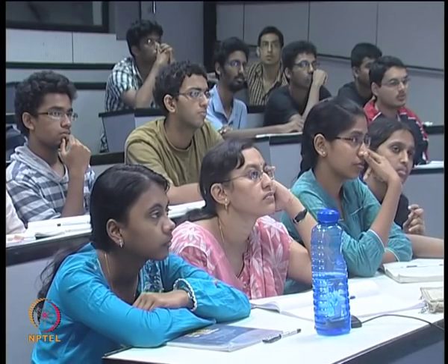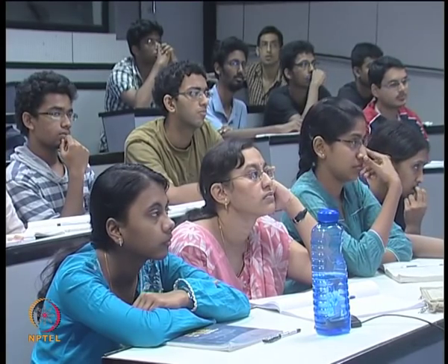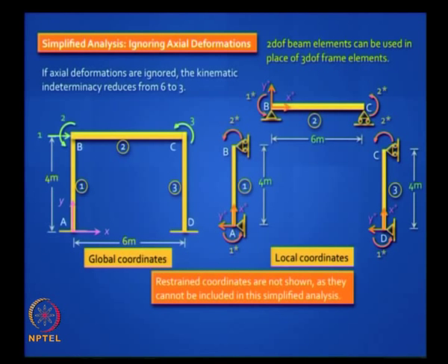In the fixed end force you have to handle it, because if D goes down by 10 mm, C also will go down exactly by 10 mm if CD is not going to change in length. BC will undergo chord rotation, and that you can get the fixed end moments from. So that is a clever way of doing it, and that is what we will do. But first, can you write down the TDA matrix? Do not worry about TDR, there is no TDR here. Can you write down the TDA matrix for the 3 elements?